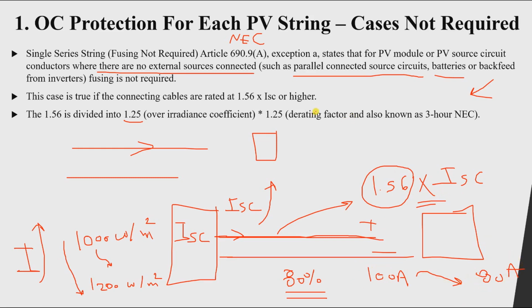So in order to choose a cable, we need to multiply by 1.25 to accommodate derating by 80%. Okay, I know you don't understand, right? Let's say, for example, that our current is 100 amperes. We need this cable to be loaded by 100 amperes at full load. So what I'm going to do is take the 100 amperes required and multiply it by 1.25. So we will choose a cable of 125 amperes.